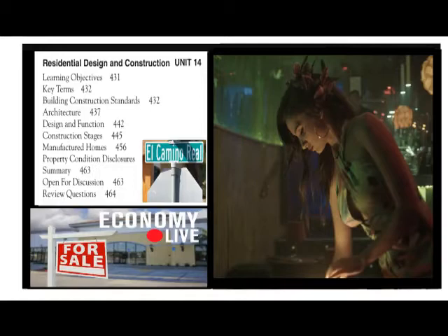Insect infestation is possible wherever wood comes into contact with earth. Termites also can build their earth tunnels from the ground to the wood structure. Along cement foundation walls or supports, the foundation itself should be chemically treated to poison termites, and any wood that must be in even indirect contact with earth, such as a fence post or deck support, also should be chemically treated and inspected regularly. As a general rule, there should be no direct contact of wood with earth.